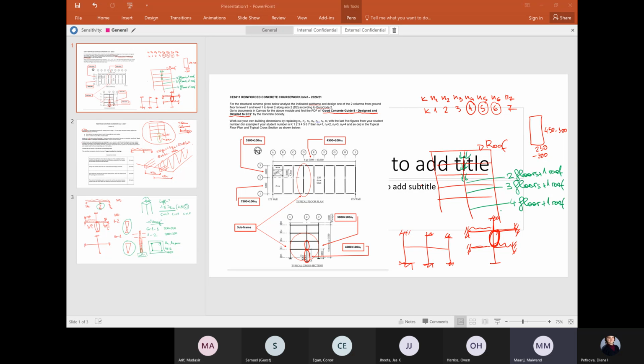So for example, if I was designing the column that was going from the basement to the ground floor. On the ground floor, I will have beams, but in the basement, I'll just have a... No, you can take it as a pin to the foundation. The idea is that if you have a rigid foundation and the corresponding connection, you could assume that the bottom is fixed.